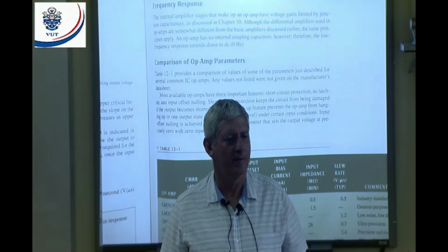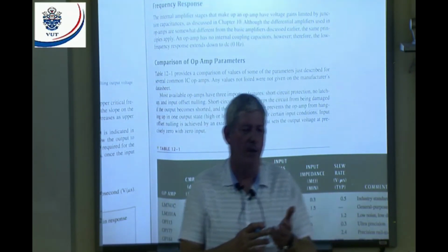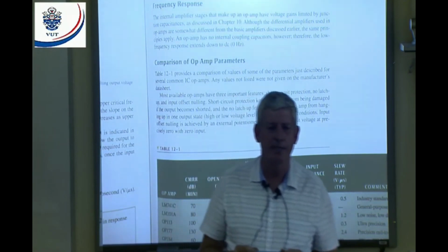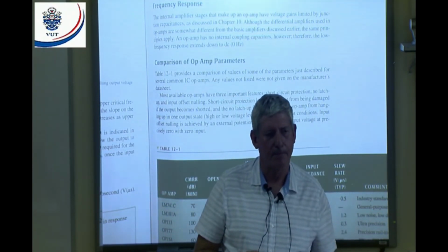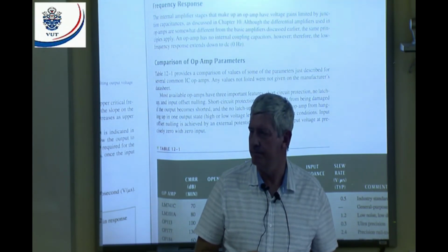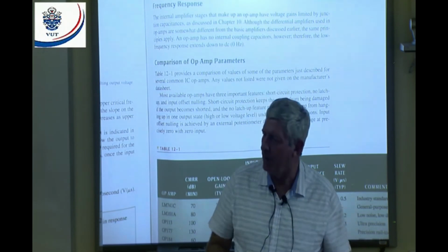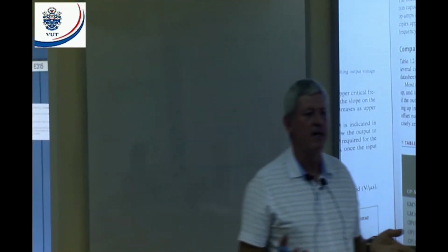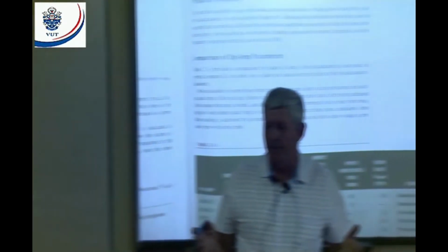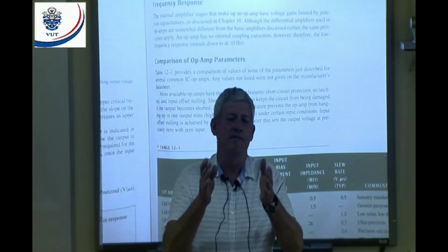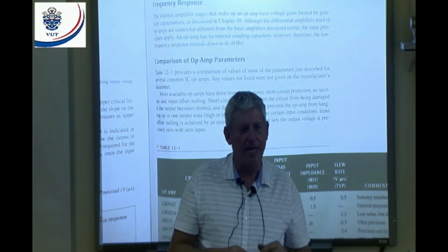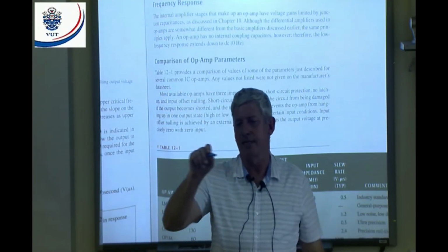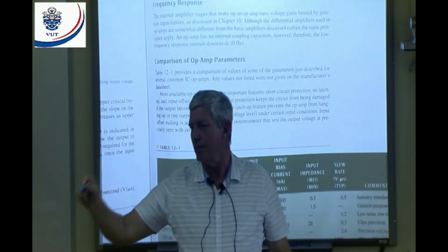All right, nobody. We have bypass and coupling capacitors. Now, at low frequencies, what can I say about my capacitive reactance? Will it be high or low? Your capacitive reactance will be high. What is capacitive reactance? It's basically the AC resistance of the capacitor. When I have high resistance, what can I say about the volt drop? It's going to be large. That means a lot of the voltage is going to be dropped across those capacitors. And that's why the amplifier doesn't function nicely. Now the frequency increases, and now it's amplifying nicely, constant. And then when I go higher and higher, it starts to drop off on the high frequency side.